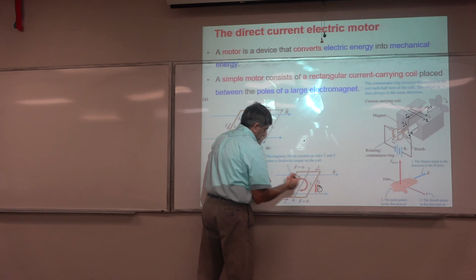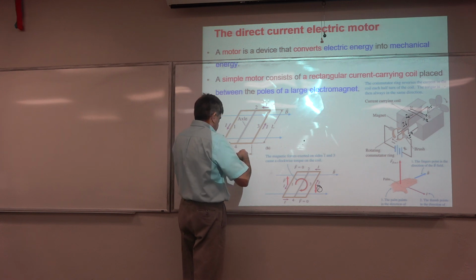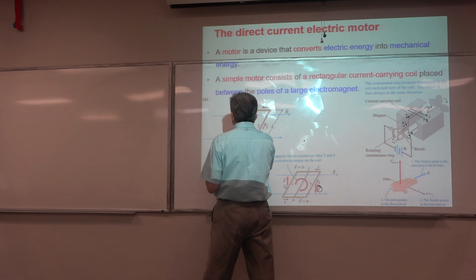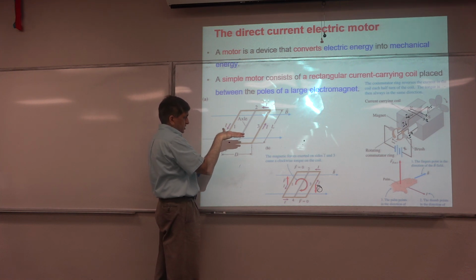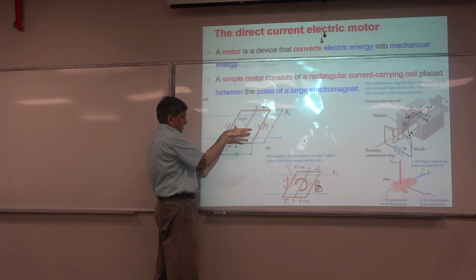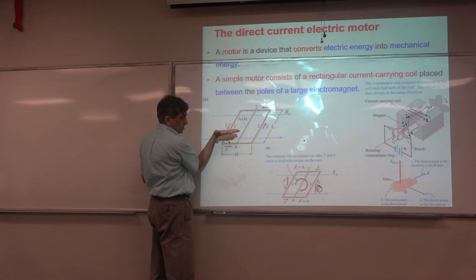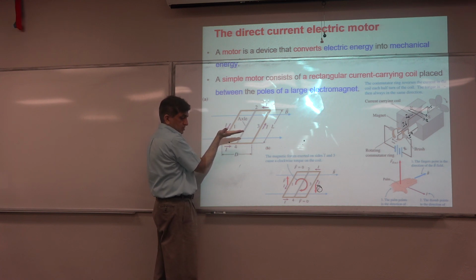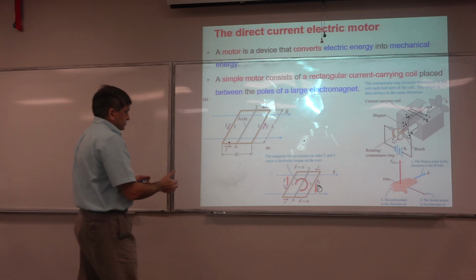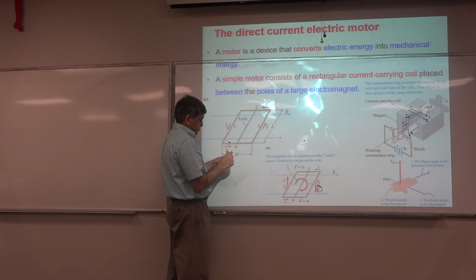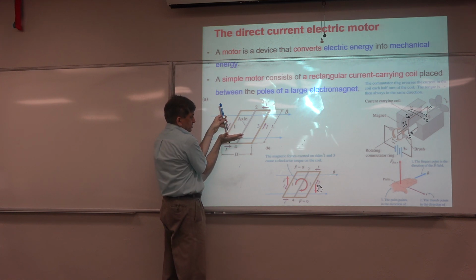Okay. Then if I come to this part, the current is going that way, and the magnetic field, basically here the current was going that way, and now in this case the current is coming towards you. This is the thumb pointing the direction of the current, and then the magnetic field is this way. So as a result, the force is going to be in the upward direction, right, here in this side.